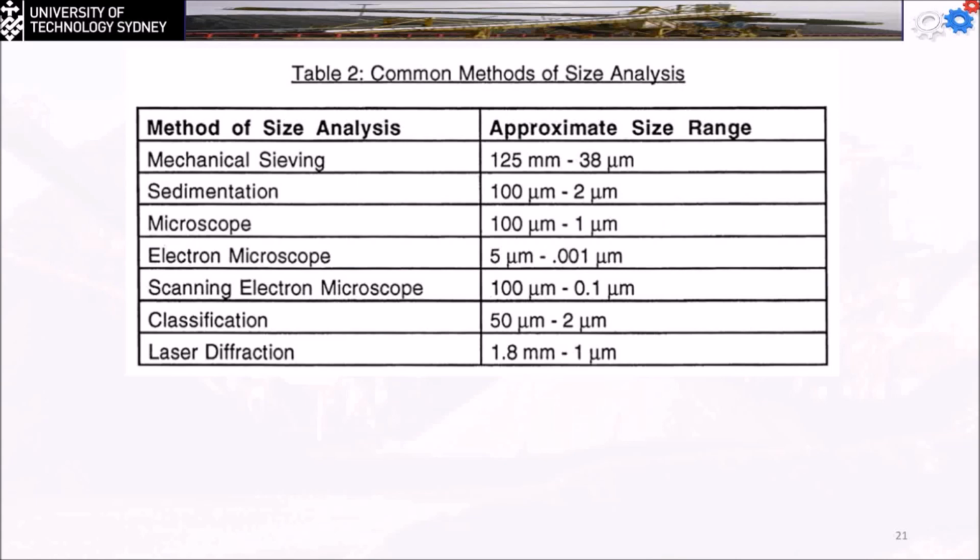Yes? Sir, recently you told us about the angle of repose, which is the study on the ground of any kind of soils or materials. But sometimes we look at many kinds of soils, solids and materials standing with a retaining wall. So is there any change in the angle of repose? Once again, it's about the moisture content you have in the sand. If it's dry sand, the angle of repose is going to be small. If it's wet, the angle of repose is going to be high, right?